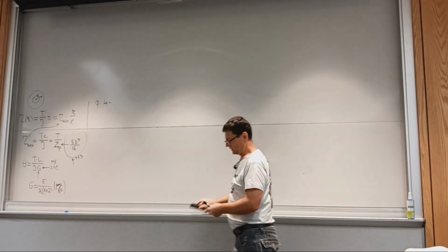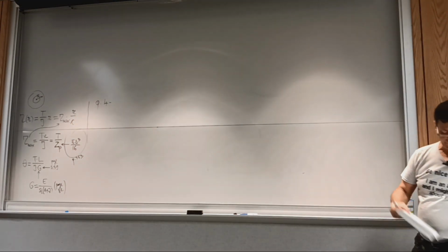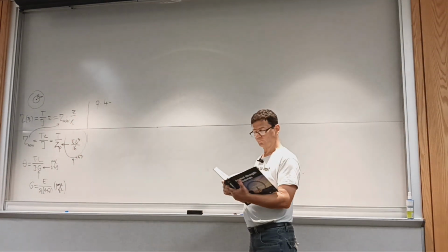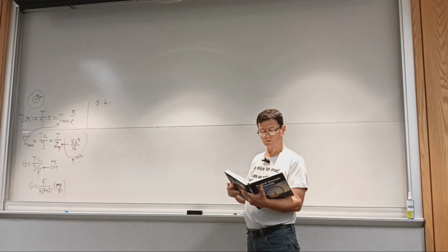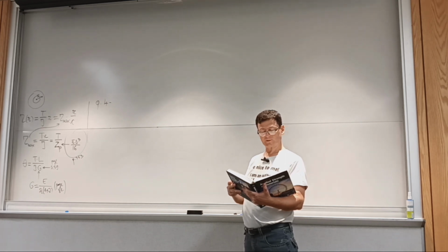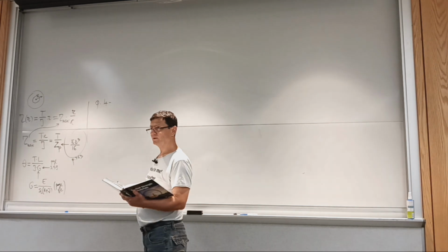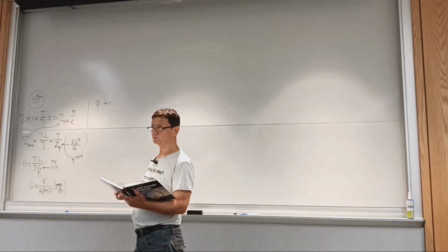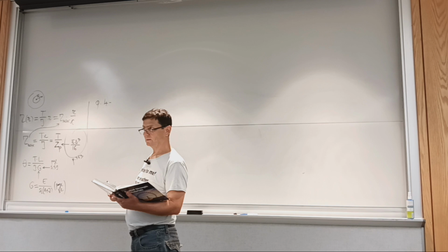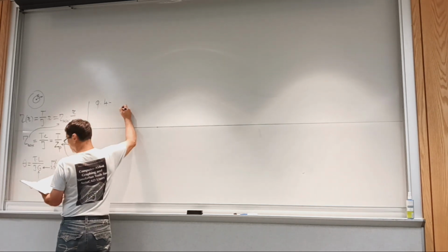And for problem 49 now, we need to calculate the torque given the power and the RPM, and then we need to account for the, there are two places where there's an increase in stress. Can you tell them? So there's one at the step. There's a transition, and I put here 0.75 inches going from 1.25. Do you have anything in your book in terms of the minor diameter where the groove is? In my book it's missing, but I put 0.75.